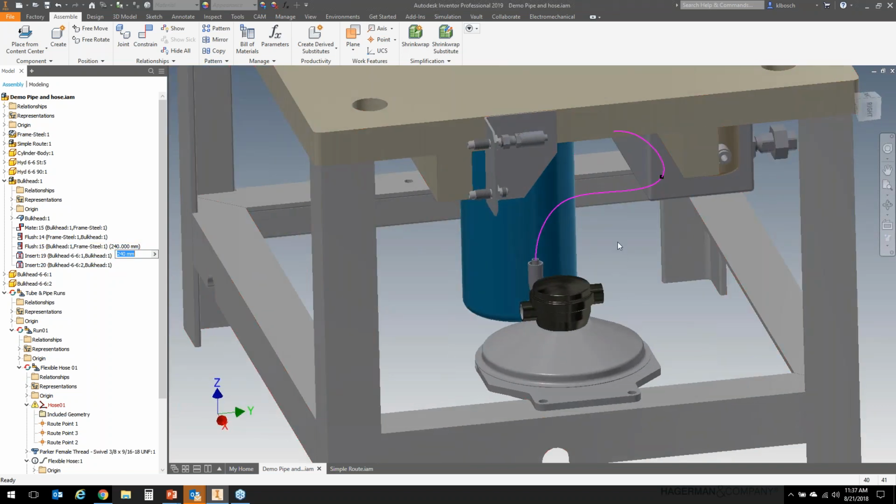The reason that my hose breaks at this point is I've got this locked, I've got that distance locked, and I've got this point defined. So I would have to go in and basically undo this, unlock that hose. I can still keep my defined point, but then make my movement, and this hose would stretch to a new length.